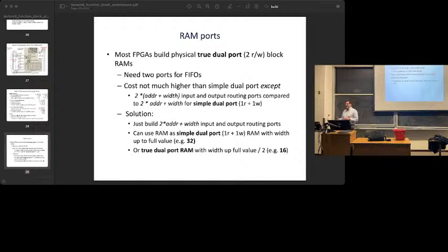Okay, so it's going to depend on what we have to add. If we had to add a lot, then probably not. If we have to add a little, then probably it's good. So let's see what we've got so far. Here's a 6 LUT. We send in 6 inputs, and I'm going to now label those as just read address, because that's what it is. And I get out 1 bit of data, my read data.